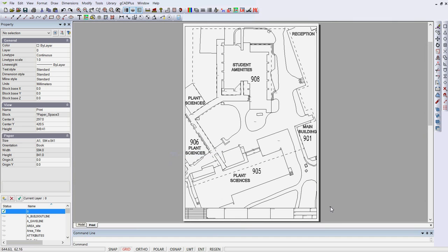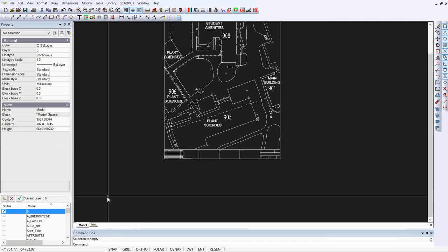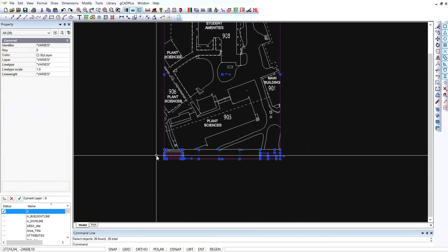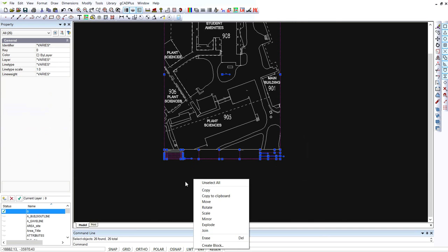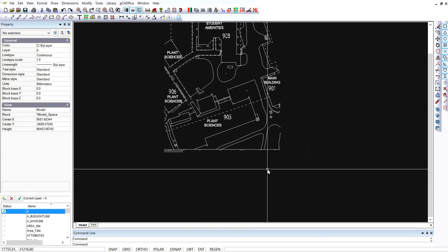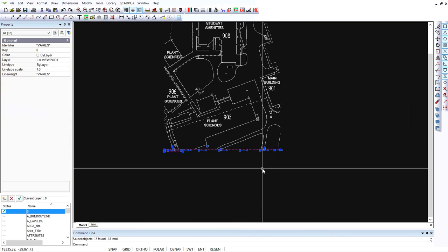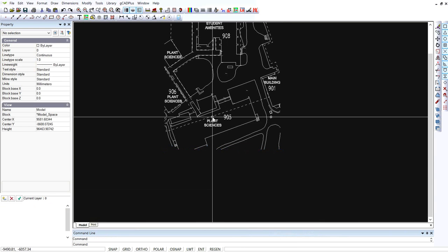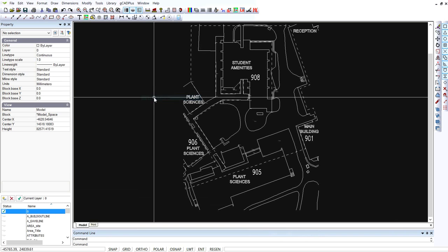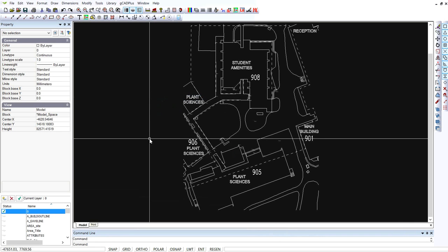If we look at this layout, can you see we can't actually select anything at all. There's a viewport, which is a view back into the model. So if we go back to the model, we should eliminate all of that information. That's not part of the Australian Design Standard. You would erase those, and we'll get in here and erase more of it. So we've cleaned up the drawing in a sense. We'll zoom extents. So the drawing's been cleaned up a little.